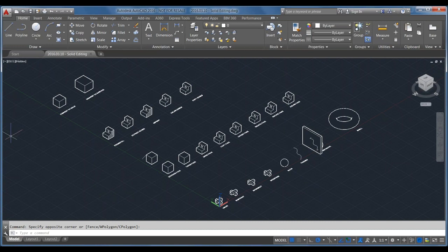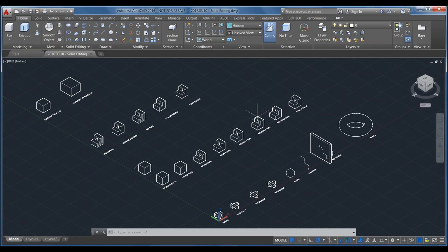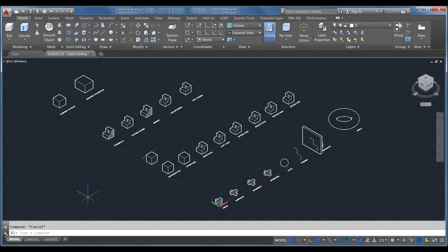So I'm here right now in AutoCAD. I just reset it to defaults this afternoon to show you how I would get to the 3D tools. So I'm going to go down here to my right-hand corner, click on the workspace gear, and I'm going to switch to, now you have the 3D Basics workspace, which we worked in before. I'm actually going to switch to 3D modeling to get to that full functionality. This has all of the 3D tools you could ever want in AutoCAD. So again, that's the workspace gear down on the right-hand corner. If you're following along, click on 3D modeling and it'll bring you into that 3D modeling workspace. And I'm just going to dock my command line so that it's not distracting anybody.